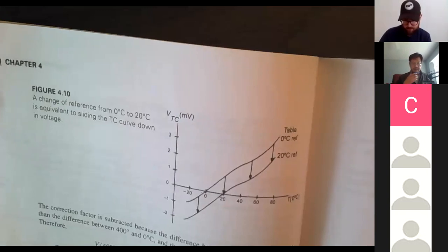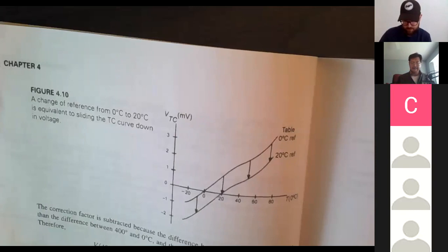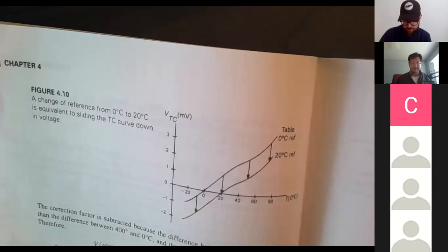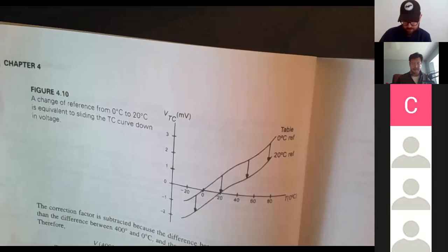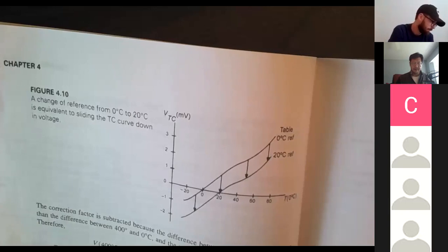So sensors are put in the can, and then wires are run out to an air-conditioned office, and we have a data logger in there that they all connect to. And so when we get new sensors, they all have to be calibrated. And so they adjust for their natural tendencies digitally.